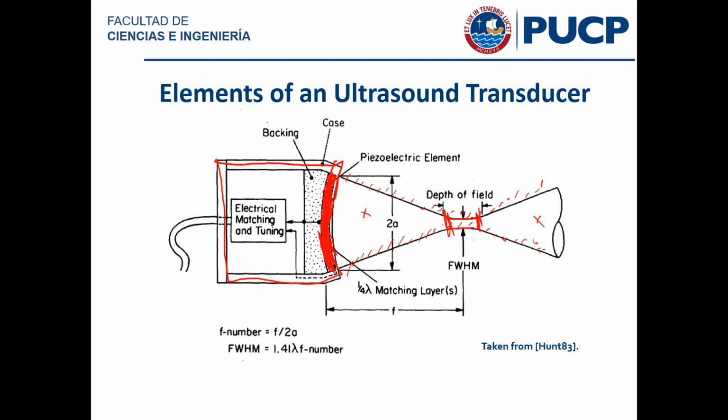And this is a single element transducer, which is something that you probably wouldn't use for medical imaging anyway. We're going to talk later in the session today about what exactly you would use for medical imaging, but to motivate the description, these basic concepts will remain the same. Together with the piezoelectric element, we have at least 2 more elements that become relevant. The first one is the backing material, which goes behind the piezoelectric element. And the second one is the lambda/4 matching layer, which goes in front of the transducer.